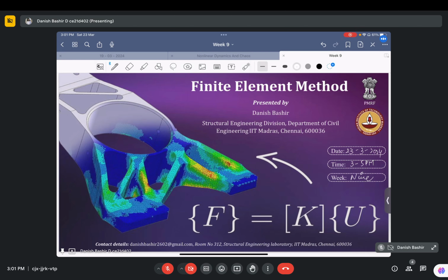In the last class, we saw a problem on beam bending, how to solve that using the element equations that we formulated the week earlier, and then we solved a complete problem wherein we had a symmetry, so we divided our problem into two equal halves and solved that. Also in the last class, we saw how we can formulate the element equations for a plane frame element. In a plane frame element, at each node we get one more additional degree of freedom, that is the axial deformation.